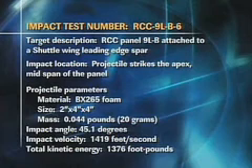I'm going to show you a pass condition, a condition where we didn't damage the target, and then I'm going to show you a condition where we did damage the target. And the reason we're showing you this is so you can see that we've demonstrated the threshold of failure for the RCC material through testing. You have to have a pass and you have to have a fail condition to establish where the line in the sand is. And so in this case, we had this 0.04 pound mass, the large piece of foam that I showed you earlier, striking at about 1420 feet per second at a 45-degree impact angle.